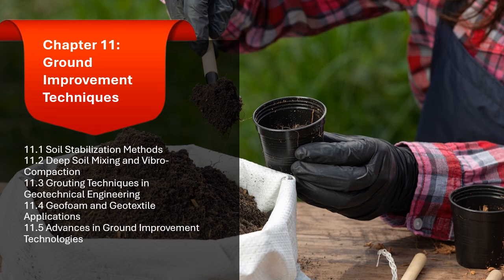3. Columns or slabs formation. The soil and binder mixture creates columns or slabs, also known as soil cement columns, within the soil mass. These columns serve as improved load-bearing zones that reinforce the overall ground structure.